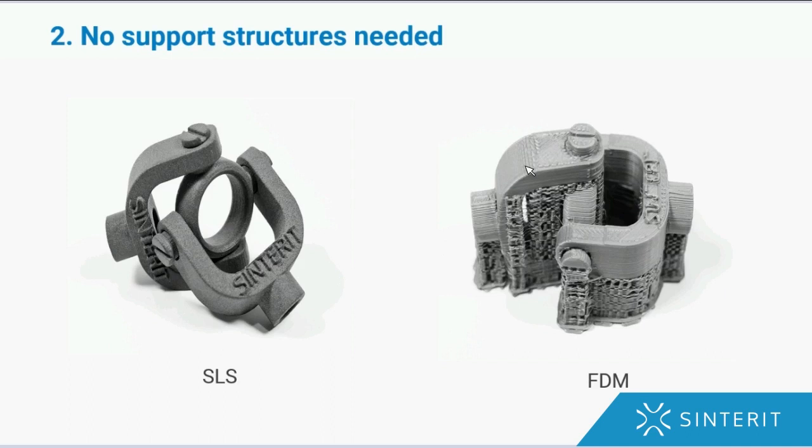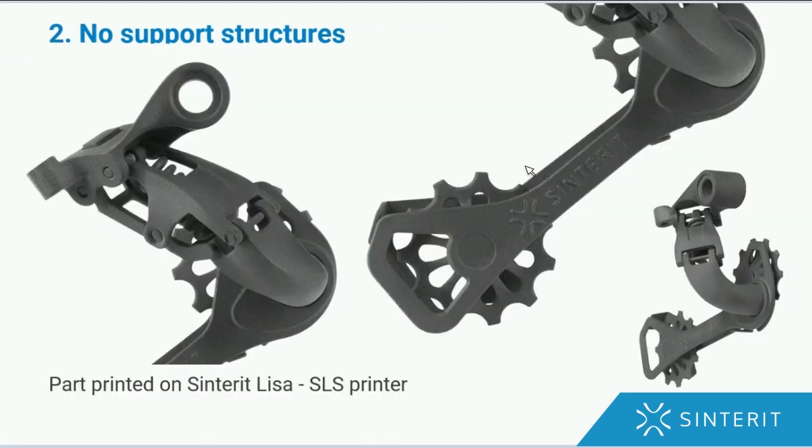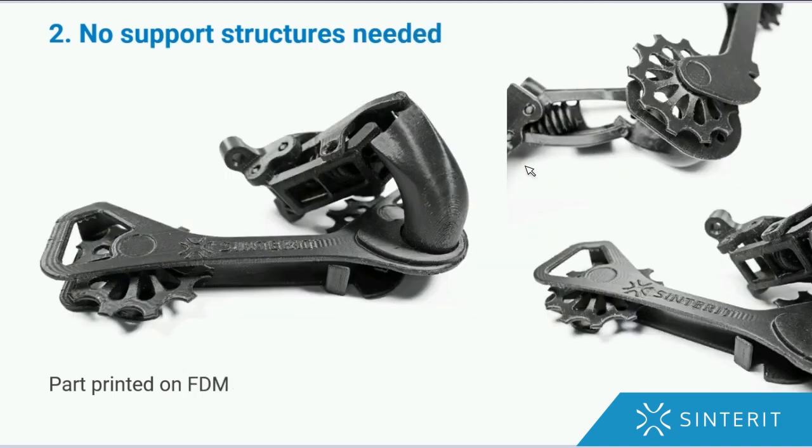You can argue that you could use a dissolvable filament to print it, but from my experience, printing supports from that kind of filament almost guarantees a failed printout, due to the fact that not many materials stick properly to them. And even if it works, you will still have undesirable artifacts in places where the support structures were present. Then there is also the warping problem and so on. And as for the derailleur, you can also see different artifacts on the FDM printout, but let's say that they are all the same quality, okay?